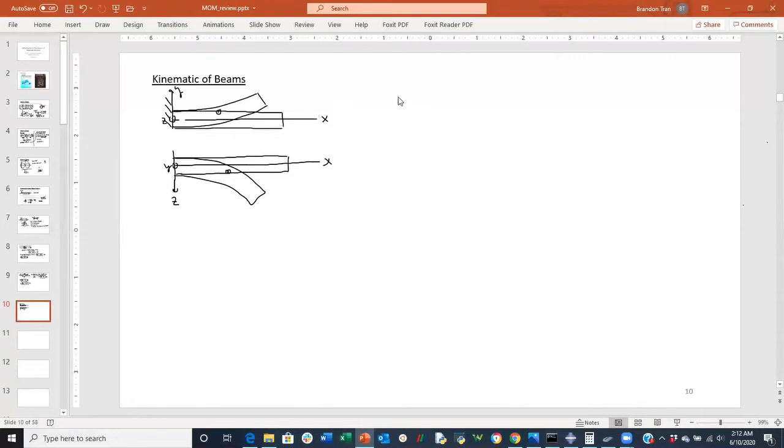The displacement in the x direction, delta x, we'll equate to the letter u. So lowercase u is equivalent to first the displacement at the middle of the beam, or the centroid of the beam. We call this a midplane strain. The midplane displacement u, which can be a function of x,